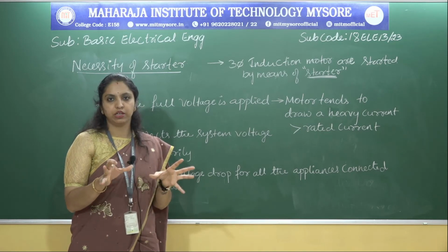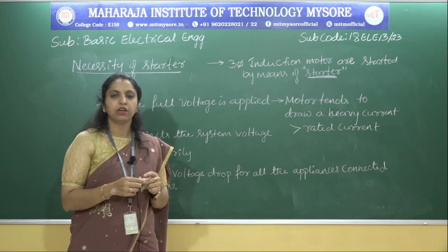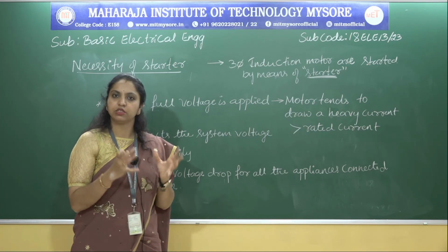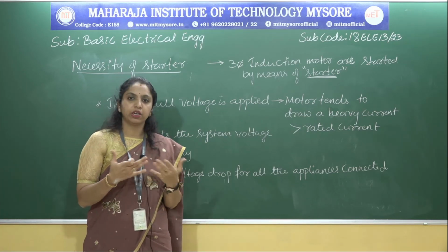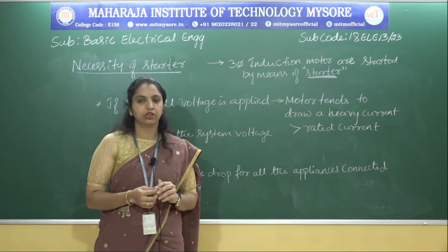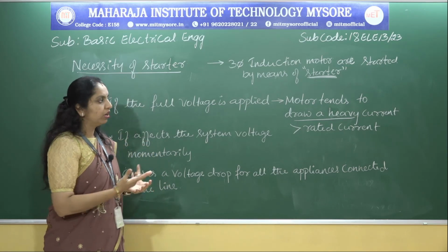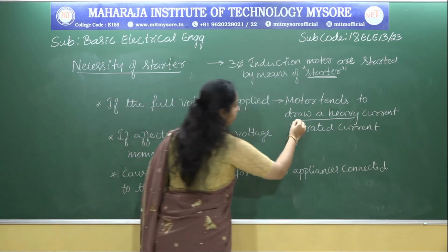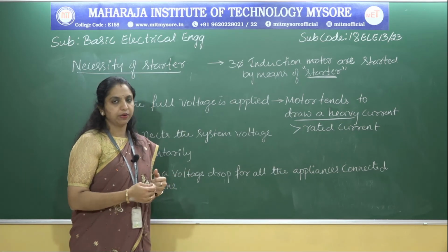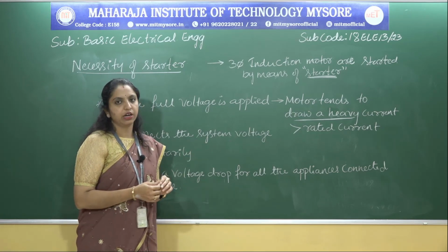Wherever you see, even in automobiles, we have a starter. What is the necessity of this starter? Whenever we consider motor operation during the normal working condition, it has the full rated voltage applied across it. If the full rated voltage is applied, the motor tends to draw heavy current, which is of course larger than the rated current.